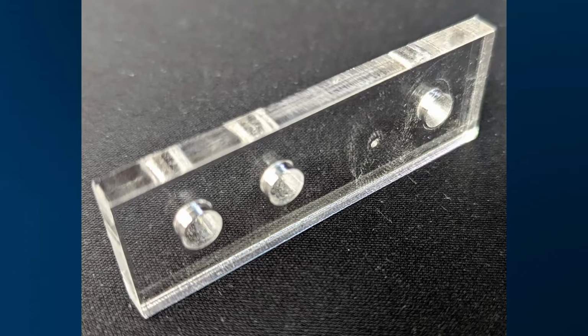Because of this, you want to make sure that any type of corrosive, even if you could pull it out of the machine, gets nowhere near the objective lens of the laser. And the objective lens is going to be the closest thing to where the beam is hitting the material. So any kind of corrosive gas that may come up, even if you could treat the gas, you still don't want inside the machine.